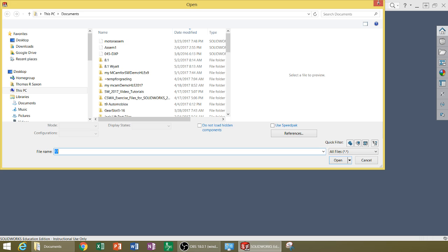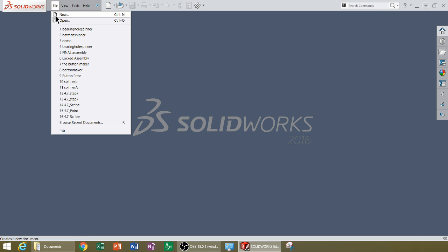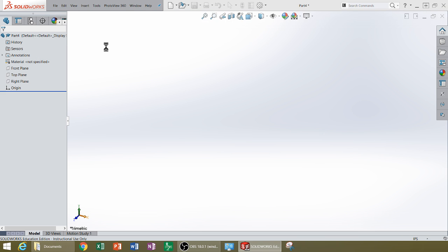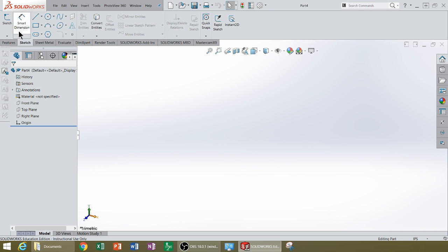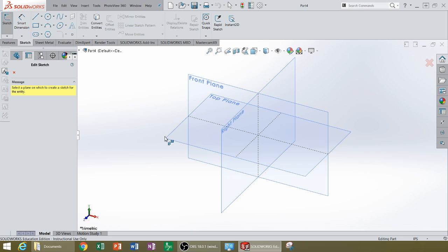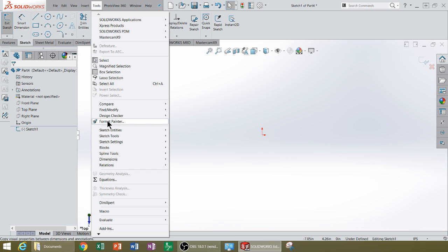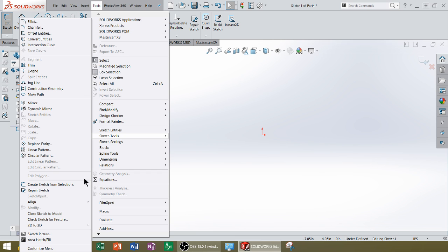start a new sketch. Sorry, I just started to open one. I'm going to go File, New, and I'm going to choose a part, and we're going to start a new sketch. And I'll show you the utility of this. I'm going to start a sketch on the top plane. Again, not important where I start a sketch. But now what I can do is with Tools and Sketch Tools, I can now bring in a picture.